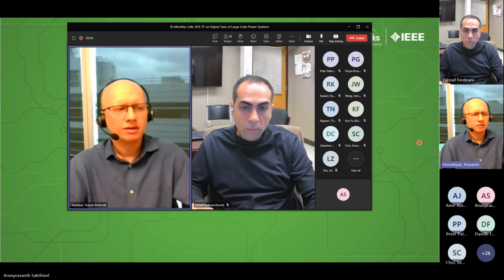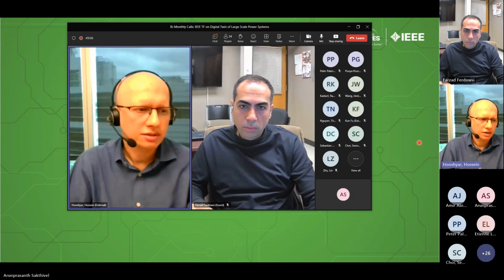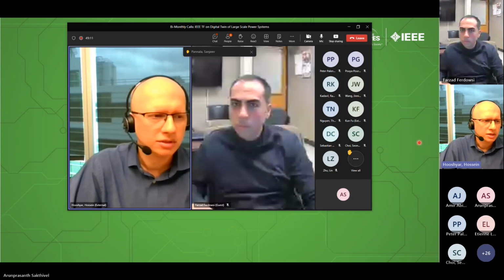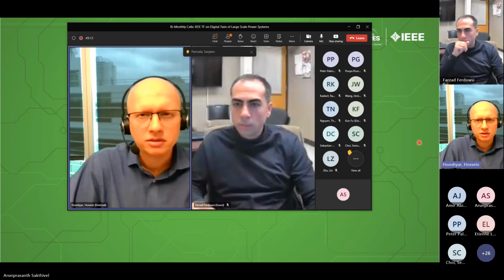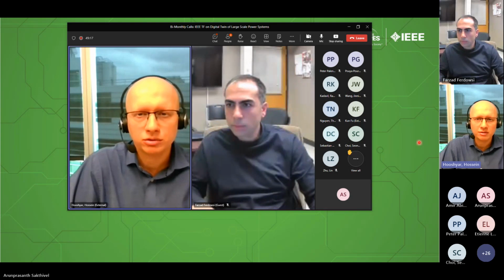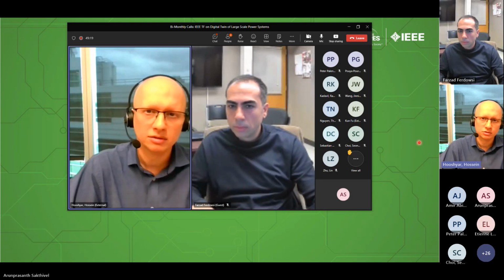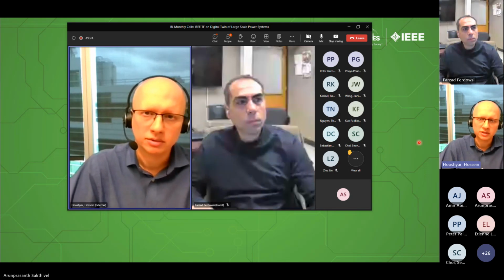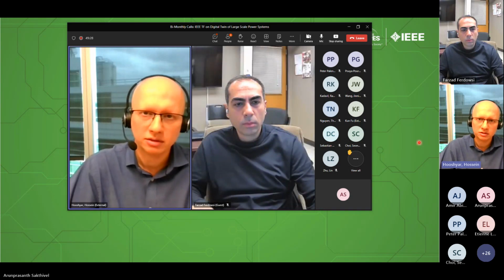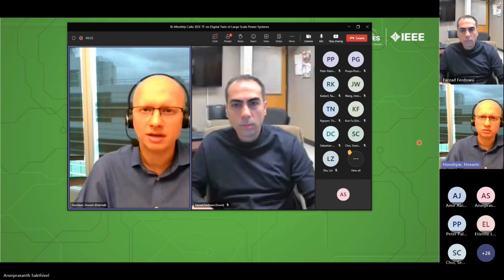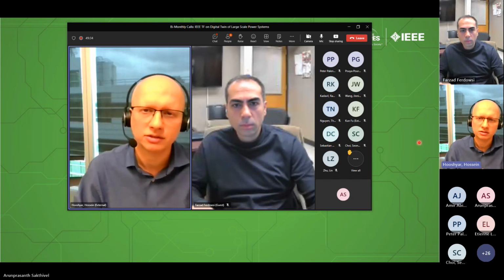Okay, and in the example that you presented, I know that you get some information from the EMS system. What kind of information is there? Is it only measurements of, for example, load levels? Do they impact the topology of the model that is running in RTDS, or no? For example, is there any breaker status measurement that goes into that to change the topology, or no? It's just the measurements. The topology is the same. Only the load levels or dispatch levels or things like that change.